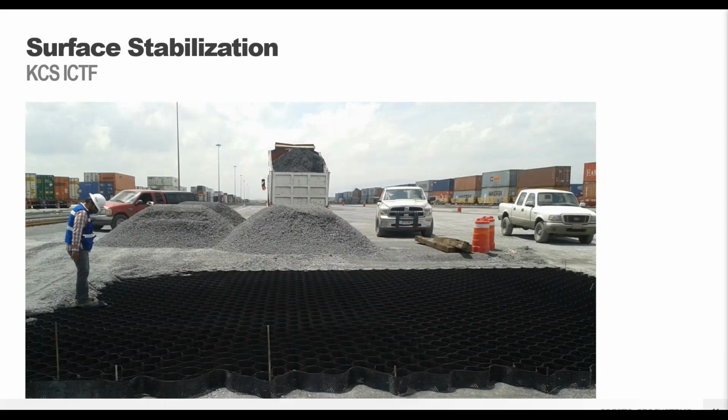So you can see how the GeoWeb panels are being infilled, in this case with crushed limestone. And the fines content here was kept around 20%. This allowed for some water infiltration into the subbase, and even it was able to keep some storage of stormwater within the cross section. This is a good photo to show that infilling process.